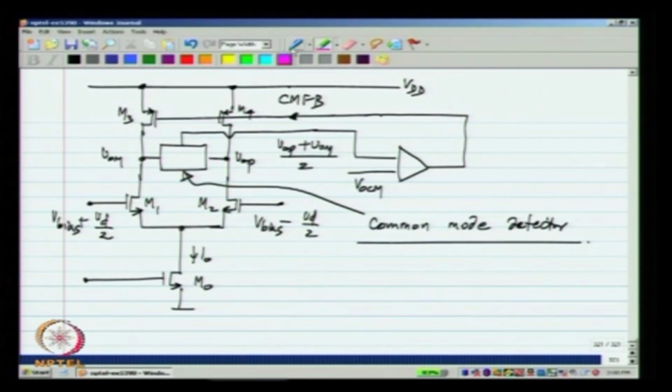Okay. So, you will see that to decrease the value of the currents in M3 and M4, we need to increase the gate voltage. So, if the output common mode voltage is very high, the common mode feedback voltage must be increased. If the output common mode voltage is very low, the common mode feedback voltage must also be decreased. So, the polarity of the op amp used in the common mode feedback is given by this. You can also determine the signs by breaking the loop and making sure that what comes back is negative and so on. Whatever I described is just that, in different words.